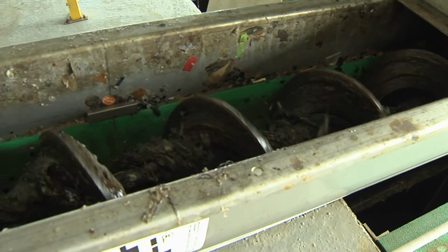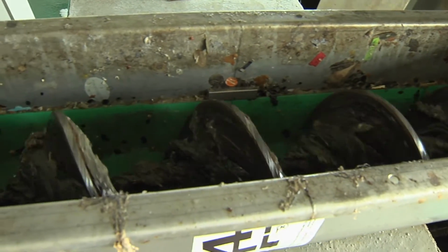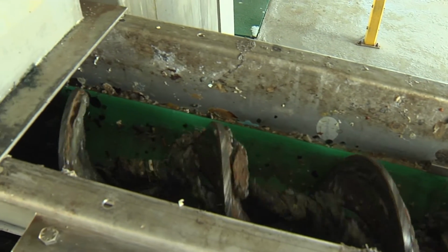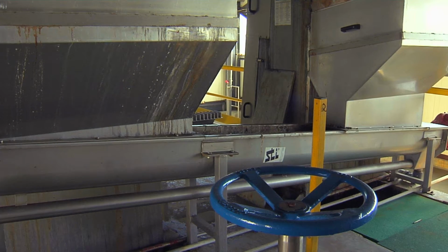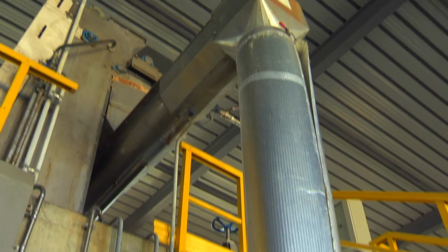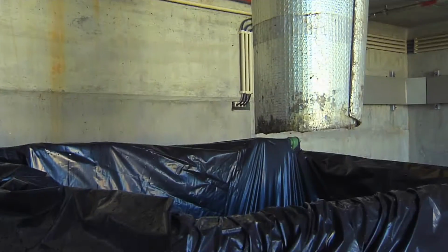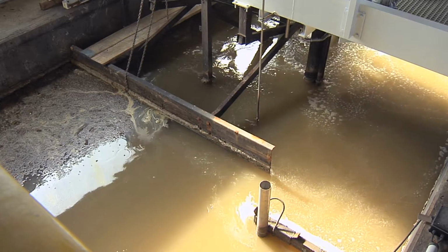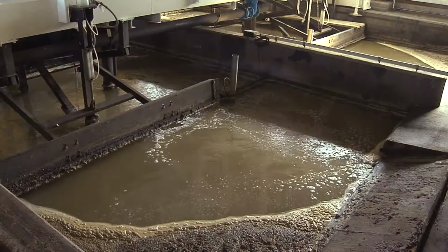Liquid phase, pre-treatment and primary treatment. During pre-treatment, coarse solids are removed along with sand and grease. The sands and coarse solids are ploughed thoroughly and packed in containers. Fats are submitted to aerobic biological treatment.